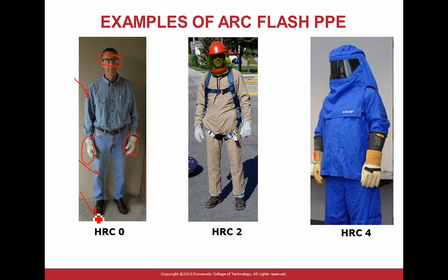To answer your question, yes, we actually have treatment for some of this, and so we're doing our arc rated shirts. If you're going to work, you can put the arc shirt over top of your polyester, because in addition to not burning, it's insulating. So the shirt that's underneath won't see that. If you wear a cotton shirt and put it on over top, and what they're providing us is arc rated, it's okay. It's not going right through it.